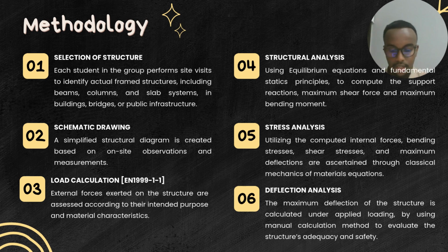Third, load calculations. External forces exerted on the structure are assessed according to their intended purpose and material characteristics. Fourth, structural analysis using equilibrium equations and fundamental statics principles to compute the support reactions, maximum shear force, and maximum bending moment.